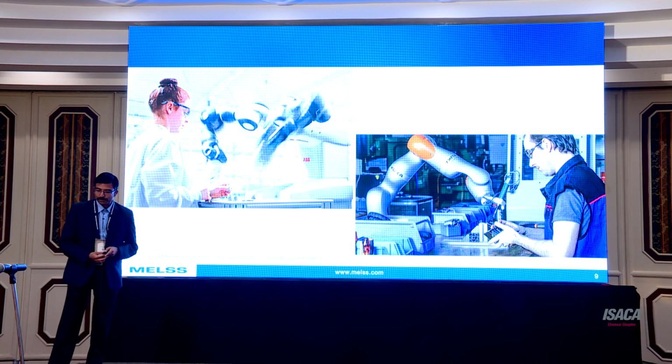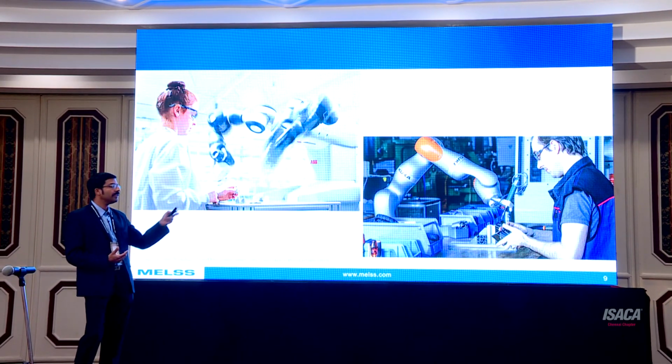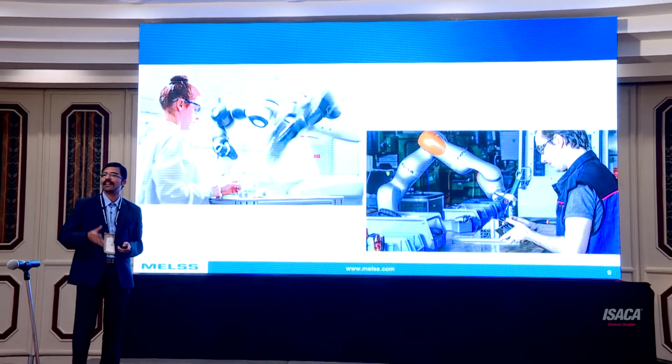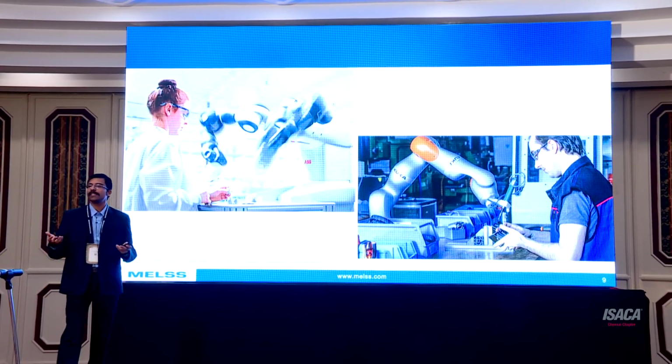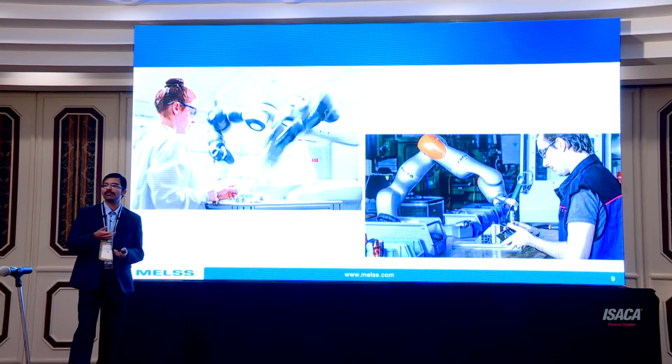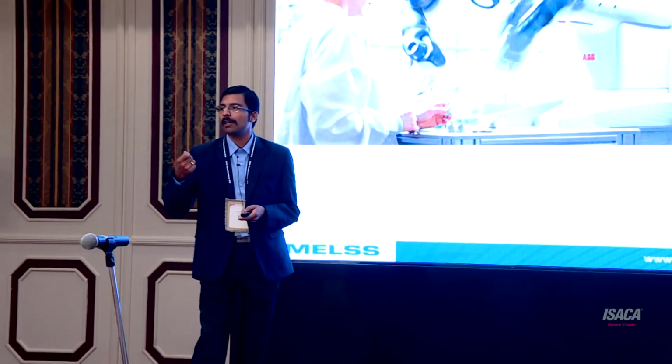So these are examples of collaborative robots being put to work. So you can see that while these robots are not normally very large in size, they don't have a fence around them, and they help humans do certain jobs. You can assume, let's say there's a jig where you need to put 100 screws inside a piece of equipment. It's a laborious job for a human to go and put these in, whereas now a collaborative robot, once a human places a jig, can start putting the screws in by itself in predefined positions, or it is made more intelligent with camera-based systems where it can identify the exact hole. Even if there's an offset, it will be able to put it right through, right?